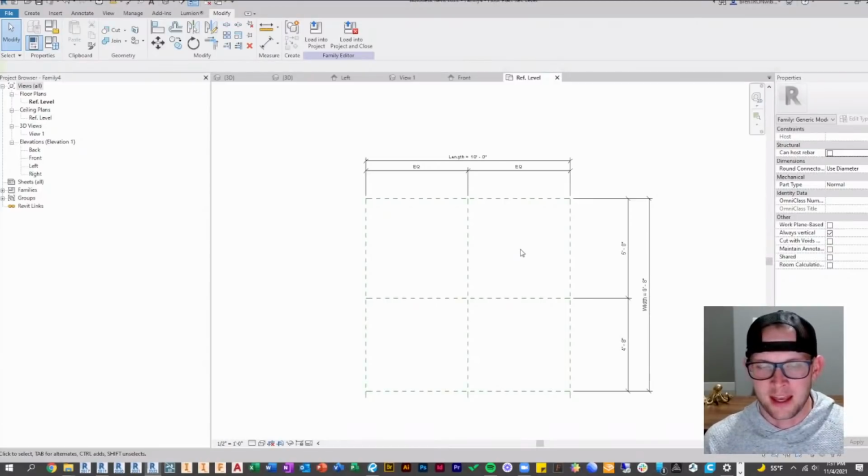I like to flex the model. And if you don't know what flexing is, it just means once you have your parameters, you change the parameters and make sure you're not breaking anything, right? I'll do little steps, flex, because you don't want to get to the finished product and it's not working. You don't know where you went wrong if you're not constantly flexing. So my first breaking point to let me know I need to flex is once I have the skeleton done.